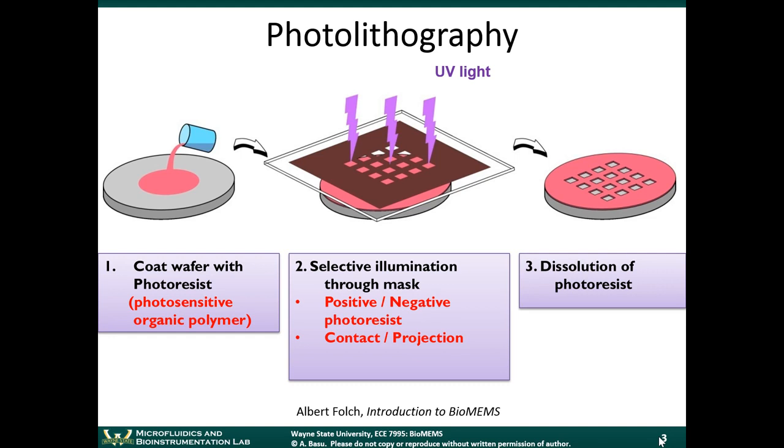All right, so the way that a typical photolithography process might work, let's say you start off with the silicon wafer over here. The silicon wafer is typically circular, and the first step is you coat the silicon wafer with photoresist. The photoresist is typically in liquid form, and you pour the photoresist over the wafer and then you spin coat it. Spin coating means that you'll take this wafer, the wafer is placed on a chuck, and it'll be spun at 3,000 RPM.